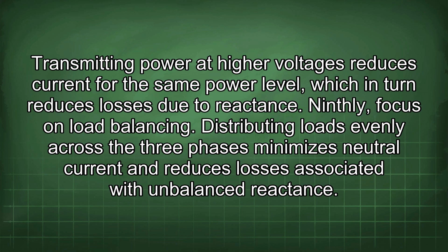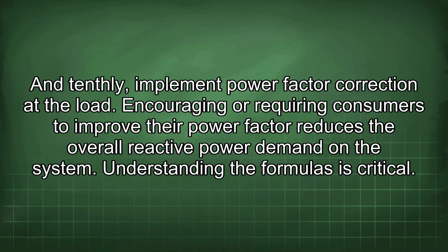Ninthly, focus on load balancing. Distributing loads evenly across the three phases minimizes neutral current and reduces losses associated with unbalanced reactance. And tenthly, implement power factor correction at the load. Encouraging or requiring consumers to improve their power factor reduces the overall reactive power demand on the system.